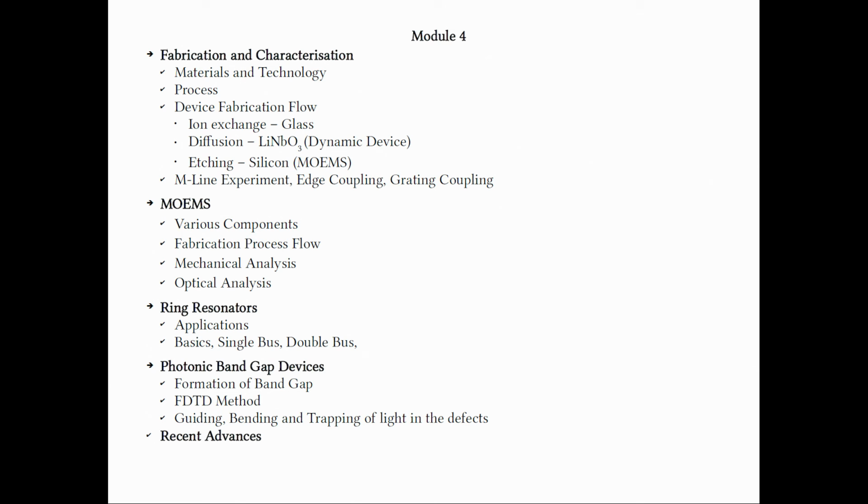One experiment we have discussed on the measurements, planar waveguide measurement, is very important to characterize the process, where we can estimate the refractive index profile, then the losses and many other factors of the planar waveguides. When it comes to the channel waveguide, we can couple it by using edge coupling through a fiber, and also more recently one of the most popular techniques to couple light into the optical circuits is by grating couplers. So then we looked at some recent topics.